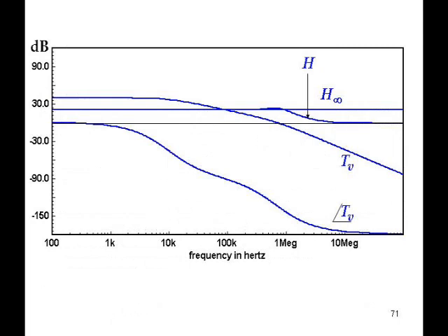There are the results that we got for the voltage injection that we just did. I made them all blue this time as a reference. And superimposed on it is exactly the same result for the current injection that I just had in the previous picture. And they're identical, because the first one was an ideal voltage injection point, the second one's an ideal current injection point. They both give the right answer.